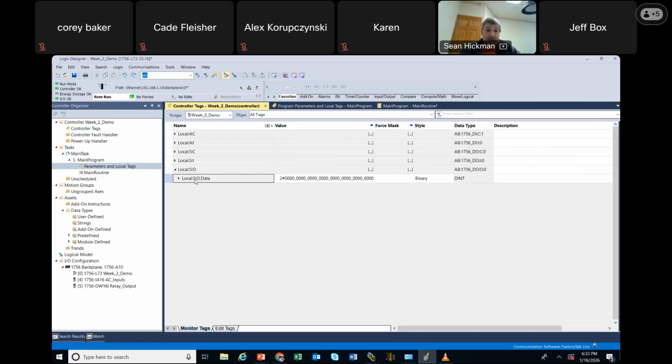But if I had my output device right here, this is my output card, and I change my radix here to decimal, and I made this right here -1, that just turns, oh, I wanted -1. How do I get -1? I want -1, unless it's a relay output card. It's all on. Okay. Yep. So a -1 right there, and that's a quick way for me to just turn all these on. This one should have been on as well.